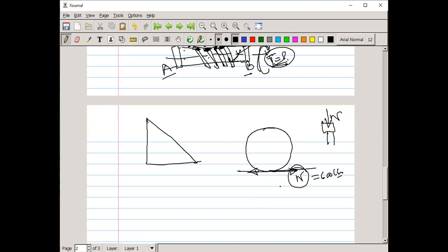Yes, sir. Okay. So see, as the load acts on this junction, that load is defined as W. Now, if we draw the equivalent diagram for this case, this is your W, and this is your worm gear. If this worm gear rotates one full revolution, and we make it linear, then this is nothing but 2 pi r. So in one full revolution, how much load will act?